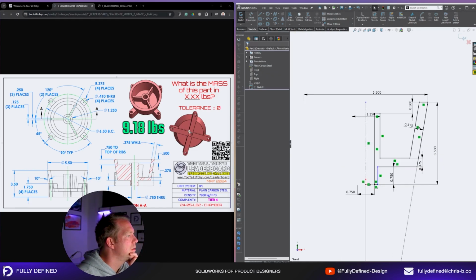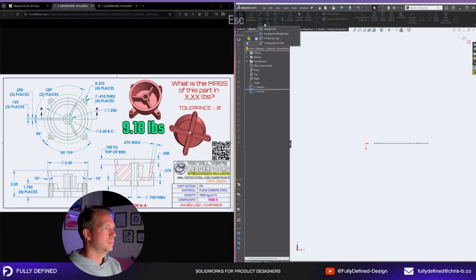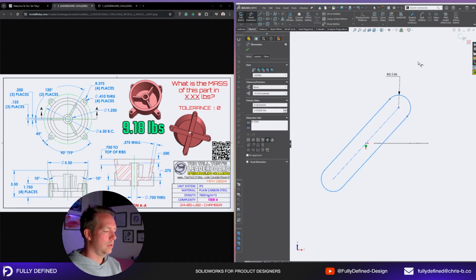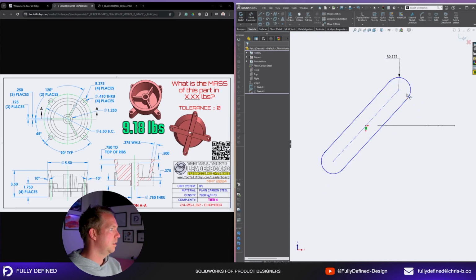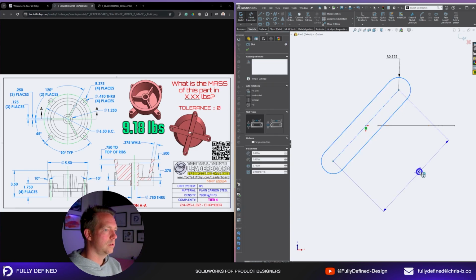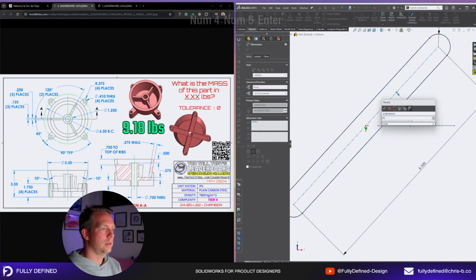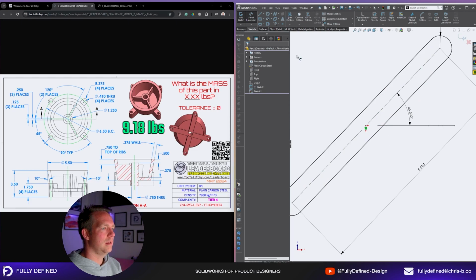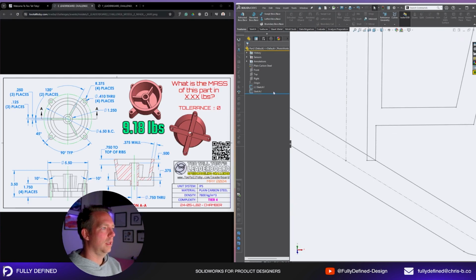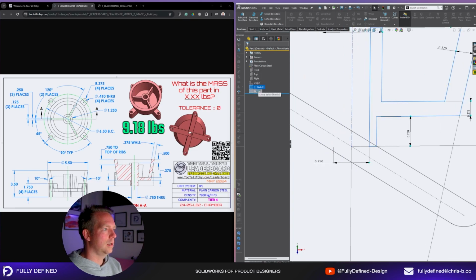Very interesting. Oh, it's the cross is what I'm seeing. Okay, so it will be controlled by the cross. And the size of the cross is 0.375 across. So we're going to have to work it out by doing something like this. It's centerpiece slot. It's going to be 3 by 8, and the size of that big circle was 6.5. So do it like this, 45 degrees. All right, and see where that line crosses right there? That's our point.